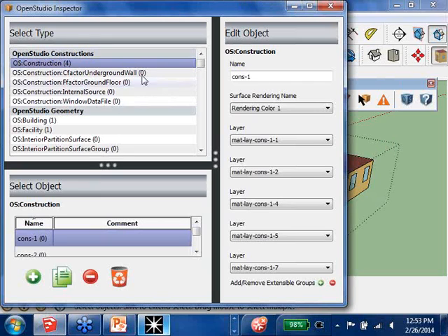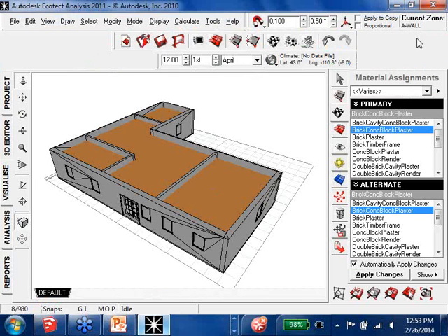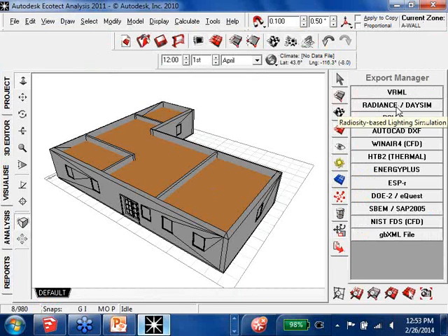But you notice with Ecotect that you could apply materials in Ecotect and run Radiance through it. With the SketchUp DXF route, you have to import the stuff, and you rename them in a way that you can see it in Radiance, so you apply materials in Radiance before you run it, right? So these different pathways have different depths that you have to go down to be able to run the analysis. So, just to get a general idea of what those are, strengths and weaknesses was the point of the presentation and of the demo.